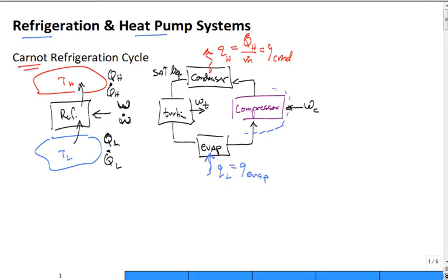You do a first law around it. It's steady state. Really, the compressor is not a heat exchanger. It's just you supply work to it. It changes the enthalpy of the working fluid. So the first law gives us that this is equal to an H going out.